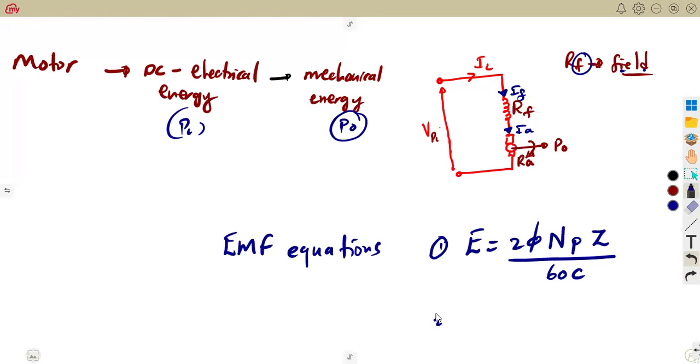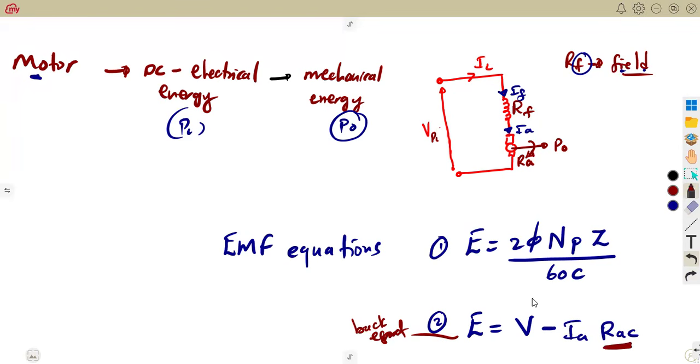And we had the one which we refer as you are to consider a motor, which is E is equal to what? V minus, remember this is the back EMF as you consider a motor, you consider this as your back EMF. So it's going to be having a minus there, and you had armature current times the resistance of the armature circuit. All right, take note about this. The resistance of the armature circuit, which is to be considered according to the circuit that you're given.